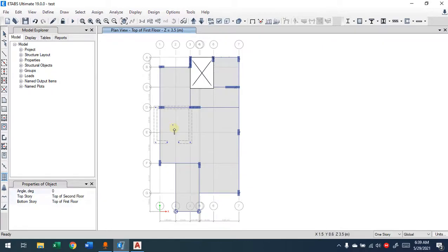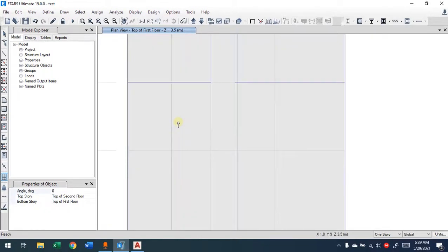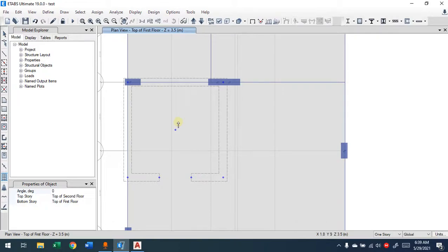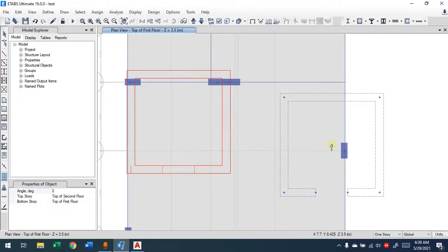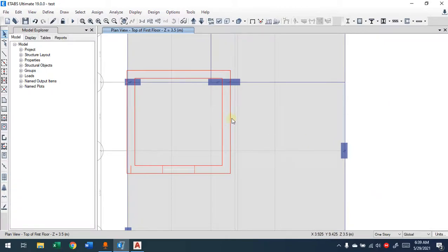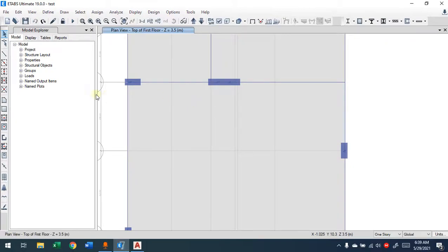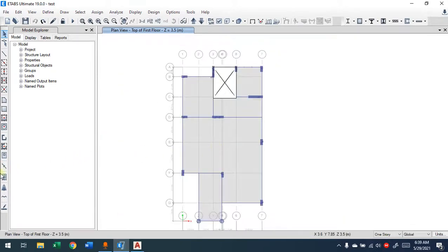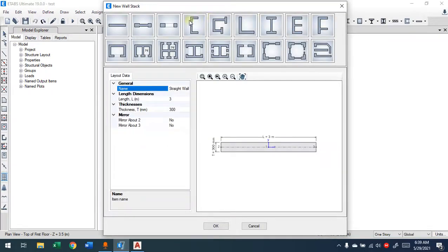Now it will give you an option basically to place it somewhere. For example, over these corners, or according to the location, let's say it will be here, it snaps to the grid and you place it here. Then you can move these things if you want to, or let's say you provide a reference point for clicking or placing the location of the shear wall. This is if you're going to use from the list here. You'll select and you place it in its location.